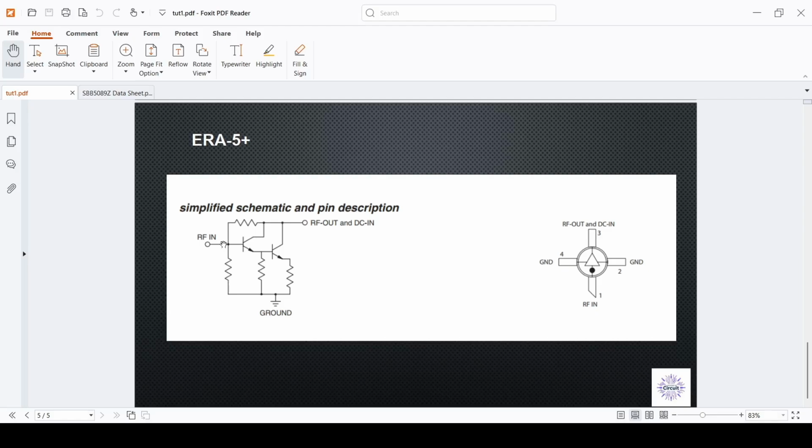The reason I'm bringing this up is I just want to show you how a wideband amplifier can be made, one of the techniques. So for an amplifier, what we need is the transistors, and here they use two transistors in series with each other. We call this Darlington pair because it gives us more current gain when we put them in this configuration.